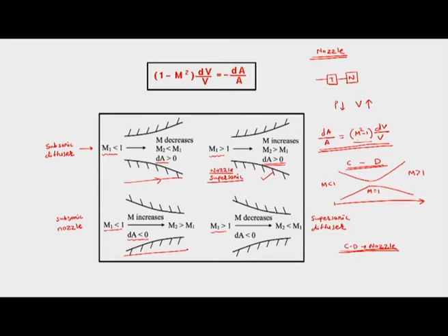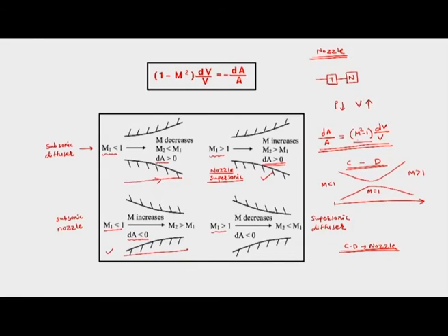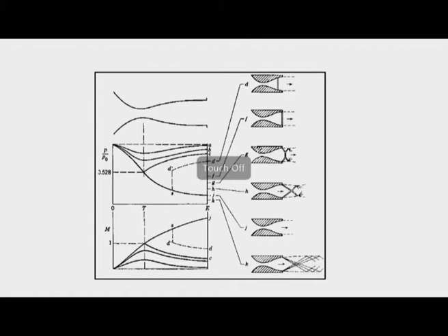Okay. So, we have to implement such a nozzle in the engine if we have such a requirement. However, in the general case, for civil aircraft at least, we see that a converging nozzle is present. So, we have only subsonic flow at the entry to the nozzle, and then it leads to a sonic outlet or maybe a subsonic outlet at the exit. But we will see how nozzle flow takes place.